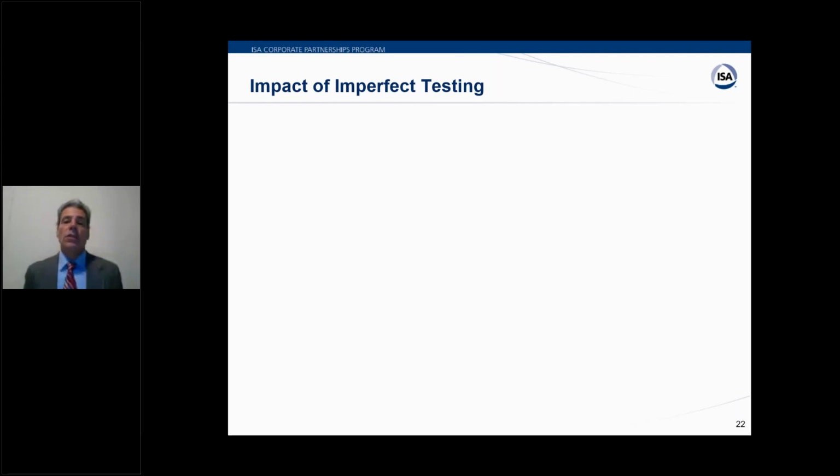Good question. The second transmitter on that tank or vessel, one was for the control system, one was for the safety system. They are completely independent. In most SIL selection techniques, for example, layer of protection analysis, you would probably take credit for the control system for doing some level of risk reduction, or it might actually be the initiating event that could cause the problem. For example, it's stuck or it's not responding. So I can't take credit for it twice. So no, we cannot count those transmitters as dual redundant.